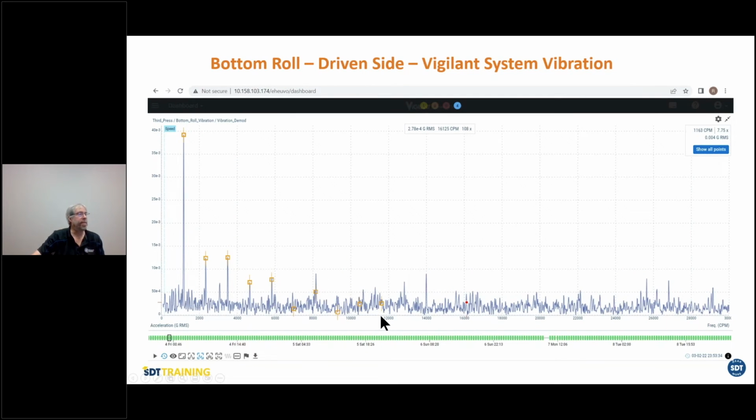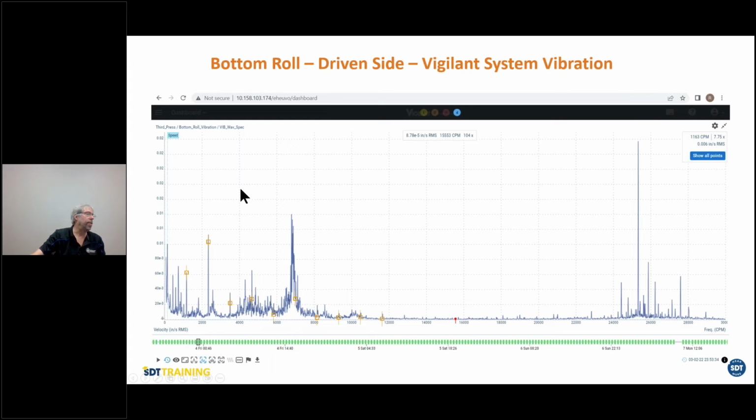This one, we can see both in vibration and ultrasound the bearing defect frequencies. So if you don't see it in one, you'll see it in the other. No matter what, you'll be able to capture your problem. Then eventually, it gets into velocities, which I explained at the very beginning of this presentation. The moment you see something at BPFO in velocity, this is the time to change the bearing. You can tolerate it inside ultrasound, you can tolerate it inside demodulation, but the moment it appears at velocity, it's time to change the bearing.